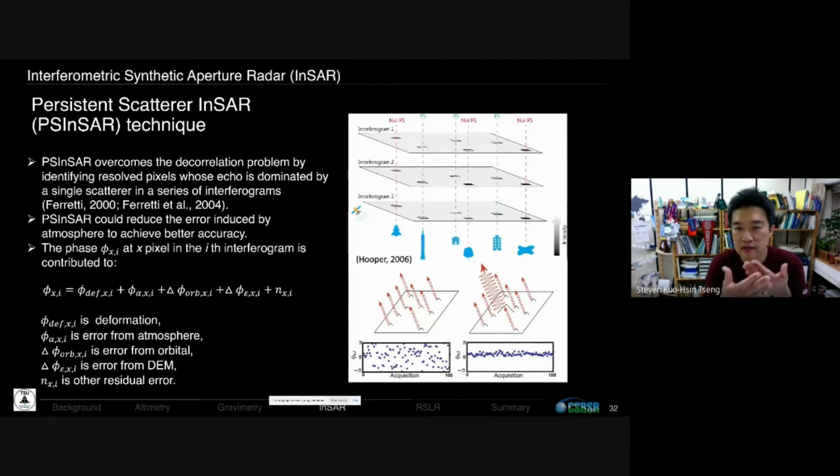So what is the phase of the bounced signal when it returns into this monostatic radar? That's the phase. And also the intensity. Intensity is a measure of the strength of the signal. So for that particular pixel, how strong the reflection is. So we mainly record these two parameters.